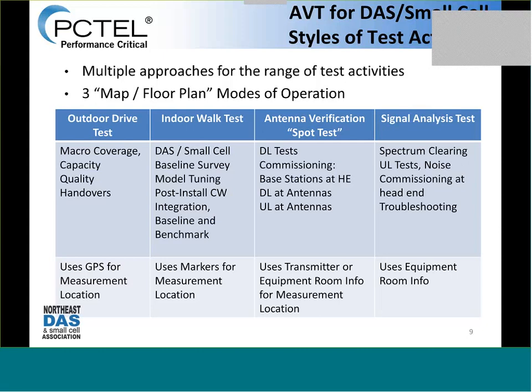And then when you get to the commissioning stage, there's a couple of other types of tests like that. The downlink test, where you're out underneath the antennas. There's an uplink test that you need to do. A lot of this time you're in the process of setting levels, attenuation values and things like that. So there's testing that's done both underneath the antenna, or you're in the head end and you're walking up to patch panels. And again, it's kind of spot test oriented, right? There's nothing walk test about being in the head end.